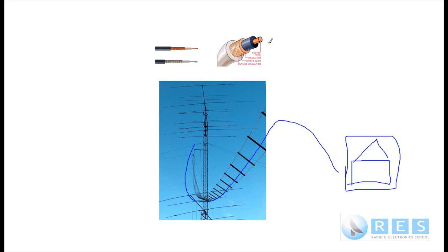The other thing you should know about parallel and coaxial lines is it is the dimensions of the cable or the parallel line which determines the characteristic impedance, and I'll talk a little bit more about the characteristic impedance shortly. As you know, the characteristic impedance of coaxial line is generally about 50 ohms. The reason why it's 50 ohms is the transmitters have a nominal internal impedance of 50 ohms, and that means that most transmitters should be connected to that impedance of 50 ohms.